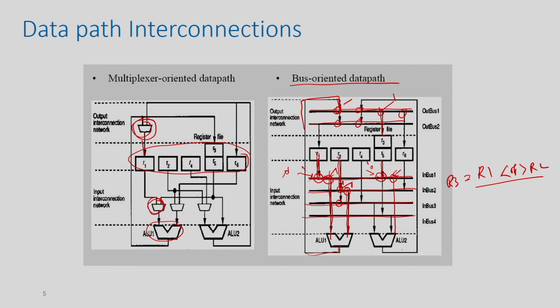So, this is how I can make the connections, and I will add the switch in every place, and then I want to make sure that in every time step, based on the transfer required, the actual RTL operations, I am going to set the bus signal to 1, and as a result the corresponding register input will come to the FU, and based on the destination register, I am going to make the switch connection accordingly. So that the output of the FU will go to the actual registers, right. So, this is the bus based connection.